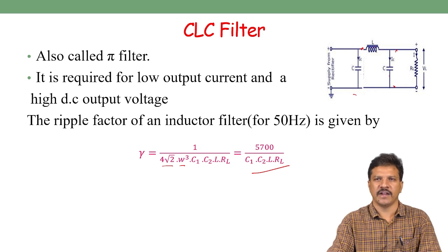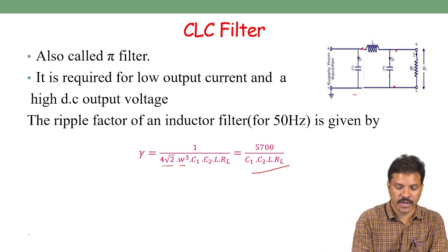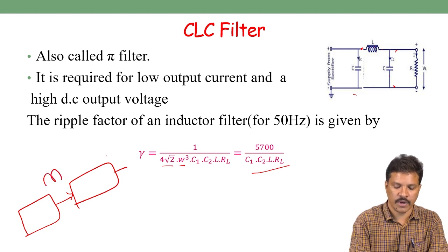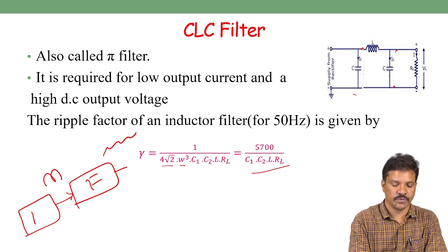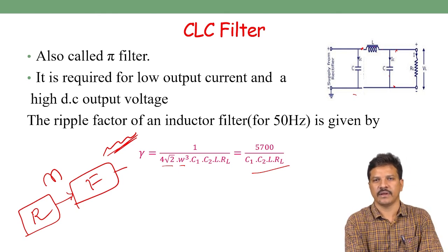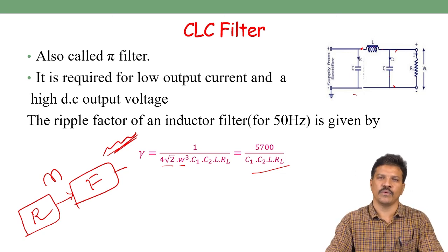So these are all filters: L filter, C filter, CLC filter, LC filter. Simply these kinds of LC resistor elements are used in the filter. When the rectified output is connected to the filter, you will get small ripples at the filter output. So we can achieve our target of almost negligible AC component. Whatever small variations we cannot filter out in the filters are then given to regulators.